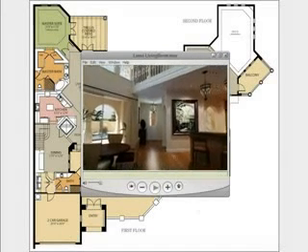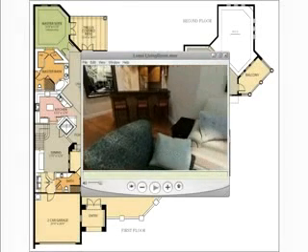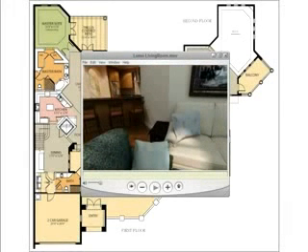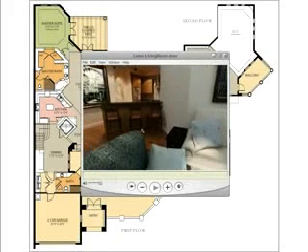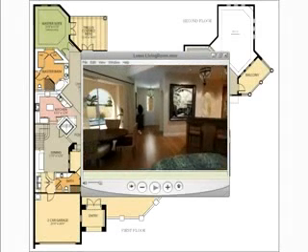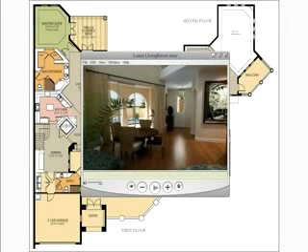Also notice in the panorama files that the rooms are fully furnished. These panoramas show the project completed, but in the max file that I'm going to be starting on, there's no furniture because just like the excluded vegetation and cars and other things in Module 9, you really need to do the majority of your lighting tests without all the extra polygons that come with this furniture. Including it in here will only increase render times when you do your test renders, and besides this, I wouldn't usually even have the furniture to place in the scene at the time I start working on the lighting.